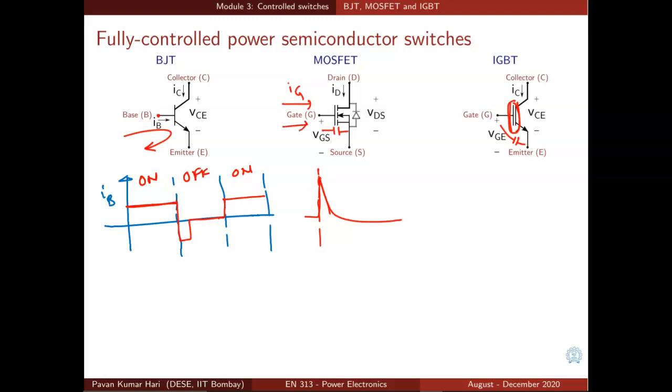to charge this capacitance. So in fact, if you have a pulse generator, something like this, one will definitely have a resistance in the gate circuit. So this is gate and we have some gate to source capacitance. To limit the current in this circuit, a resistance is kept. This is usually known as the gate resistance.